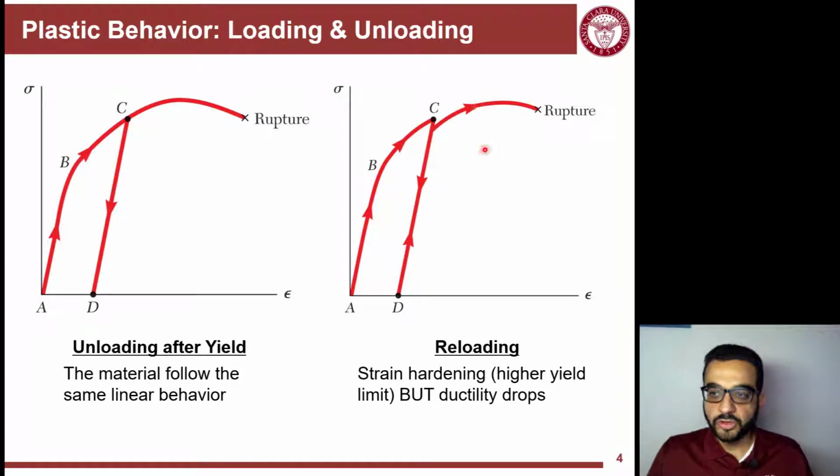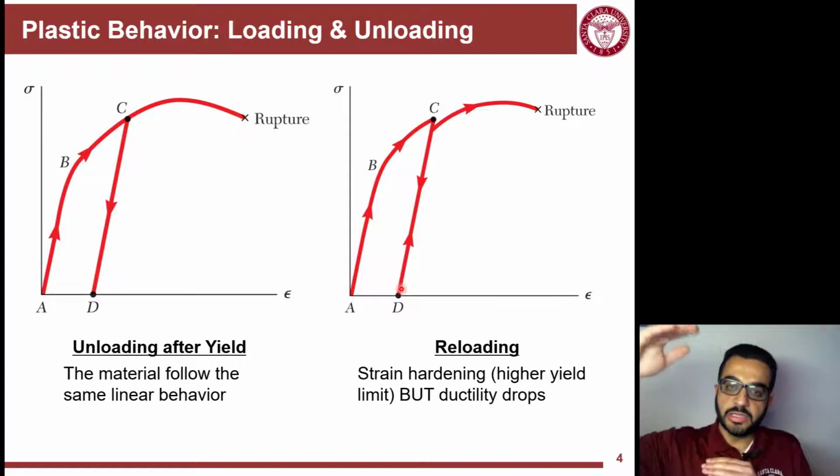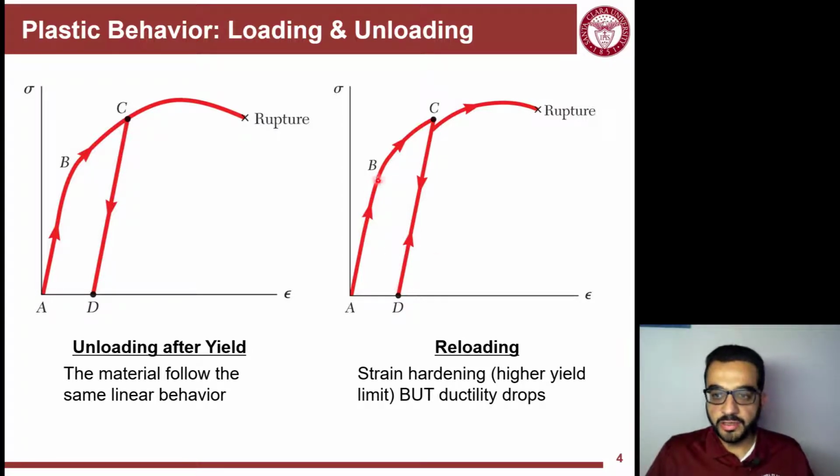curve that you have. So the idea here is that you're making the material harder. You're increasing your yield limit. So instead of staying here, you did that on purpose. Kind of, you made the material go into the plastic region or harden and let it go back, have some permanent deformation, but when it's being loaded again, you will have more ability to load it in the elastic region by lifting up your yield limit. But the downside of that is your ductility now is reduced.